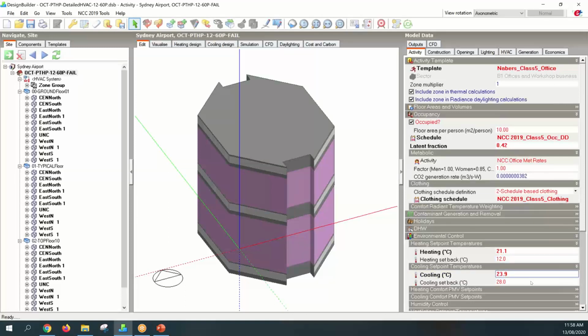The reason I've got it to be 0.1 degrees centigrade more and less in the cooling instance is because energy simulations are iterative, and whenever you see a number that is 24.0001, that'll be counted as an hour that the criteria is not met. So just to avoid some of those idiosyncrasies with the simulation model, I've just put it so that it captures all those ends of the spectrum.